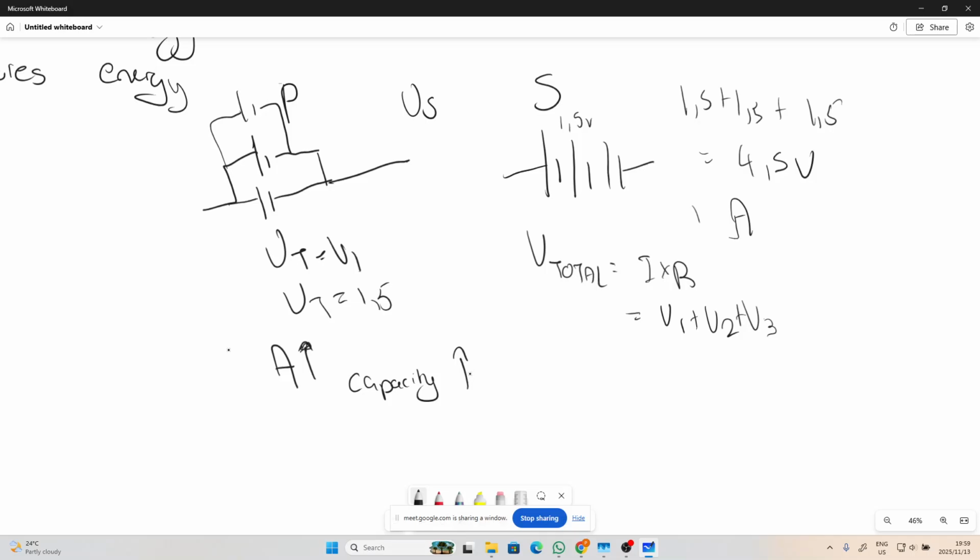For example, your phone battery might use combinations of this to get, I don't know, maybe 12 volts or whatever voltage your battery is, for increased capacity and increased voltage. Parallel if you want more battery capacity, your batteries last longer this way. Series if you want more voltage, your batteries get more voltage through your circuit this way.